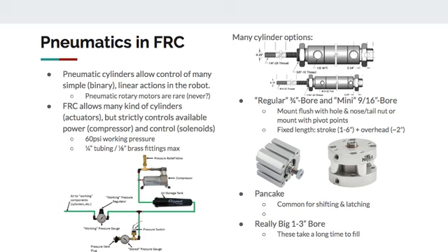They have a solenoid max valve size and max tube size of 1/4 inch. I couldn't actually find the max tube size rule, I just read it a day ago. I remember it being there, but I'm sure it's there somewhere. There's an explicit rule that says your solenoid can't have more than a 1/4 inch tube or 1/8 inch hard connection. And that one's been there forever.